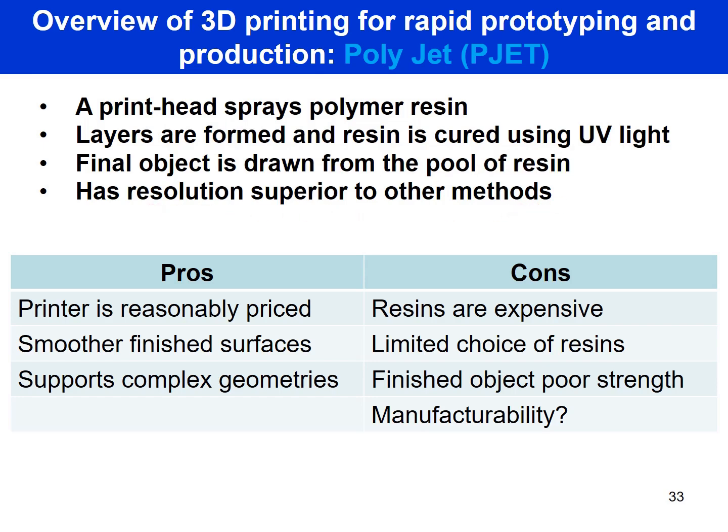The advantages are that it's reasonably priced, the smooth finished surface that is provided, and it does support complex geometries. The disadvantages are a limited choice of resins, the finished object has poor strength, and manufacturability is still under question.